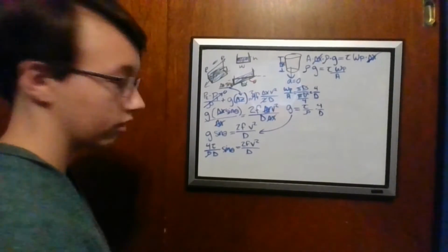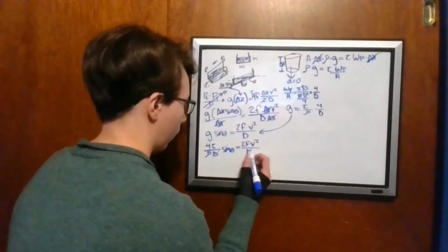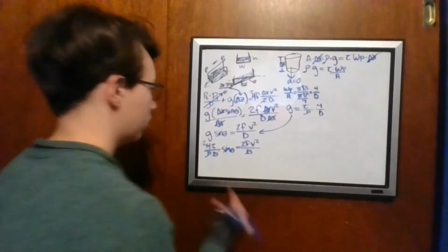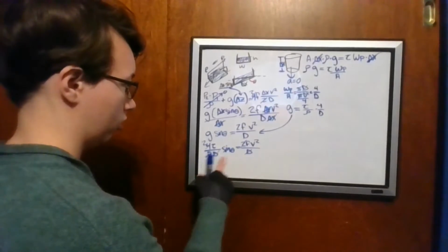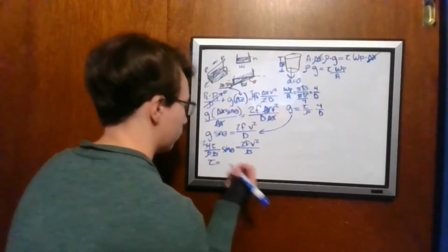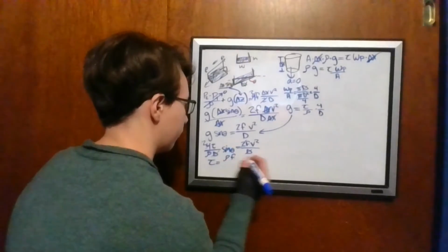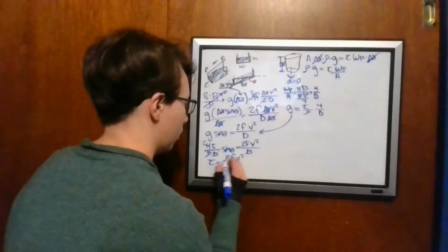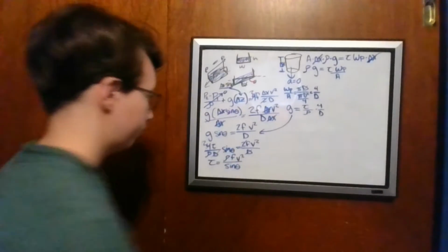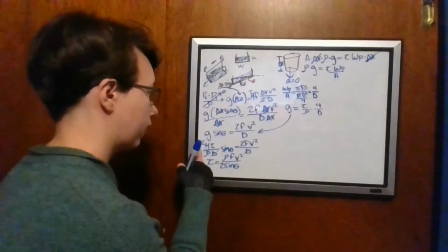So you can see a couple things cancel out. It's just the diameter cancels, and this coefficient also cancels. So we can solve for this tau by multiplying this rho over and dividing by the sine theta. So we have that the shear stress is equal to the density times the fanning friction factor times velocity squared over, sorry, over 2 sine of theta. There's that 2 up there.